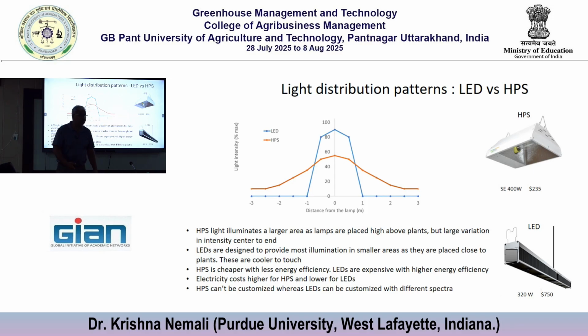So what experience tells us is you may invest more in LEDs initially, but in a span of 10 years, you will recover the cost because you are paying less every month for electricity. That is the major benefit. So over time, the benefit shows up. And therefore, these LEDs are becoming very popular. There is one other thing I want to mention. The bulbs inside these HPS lamps, I think their life is only 2 or 3 years. Afterwards, you have to replace the bulb. But the LEDs have a much longer life.